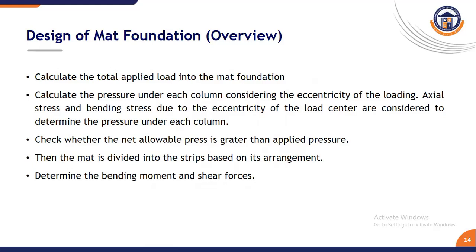Okay, in the conclusion, the summary of the presentation: raft foundations are used when the soil is weak and heavy loads need to be spread, and they minimize differential settlement and are suitable for high-rise, industrial, and water retaining structures. Then they require proper design to resist bending, shear, and uplift forces.